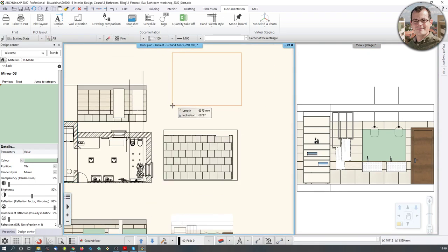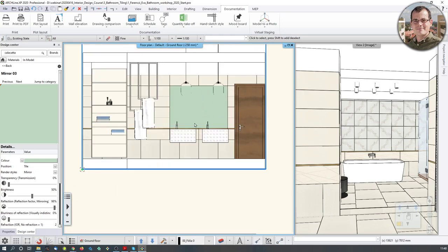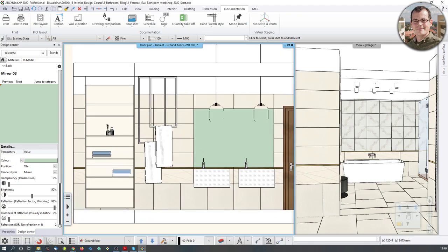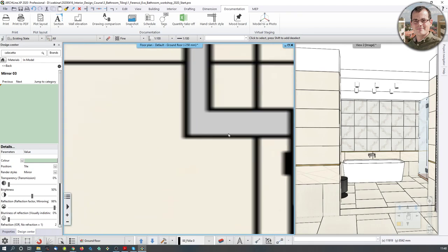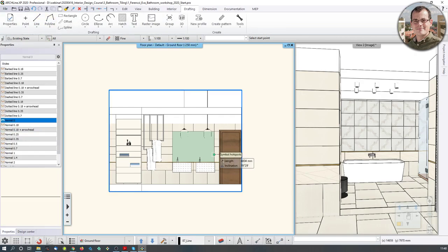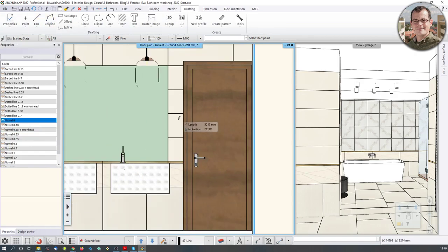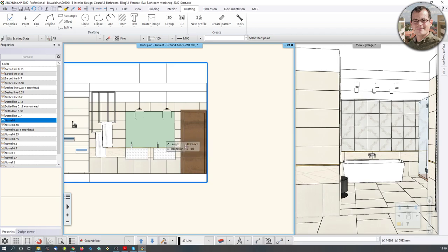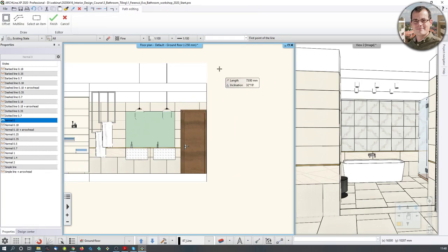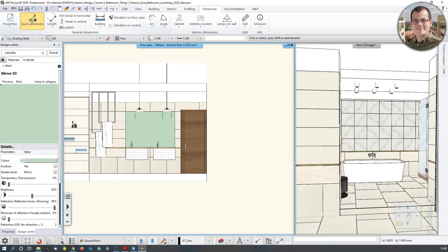And the drawing is placed. Now, one very important thing about this drawing is that it's not vector-based, it's an image. So if you zoom in, you see that it's going to be blurry. However, if you want to draw additional things on it, you see that the software is going to snap to the points. So this is sort of an in-between of a drawing and an image, because if you, for example, want to make a quick dimension, let me just do that real quick,